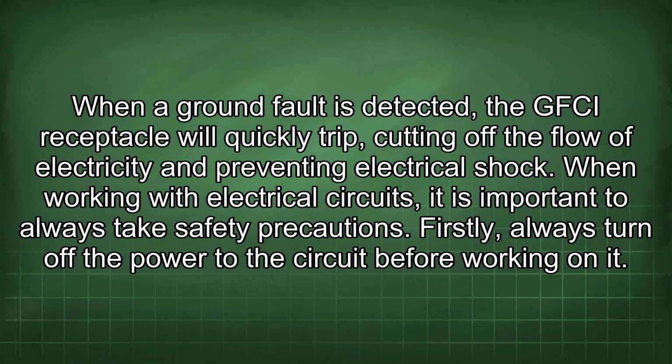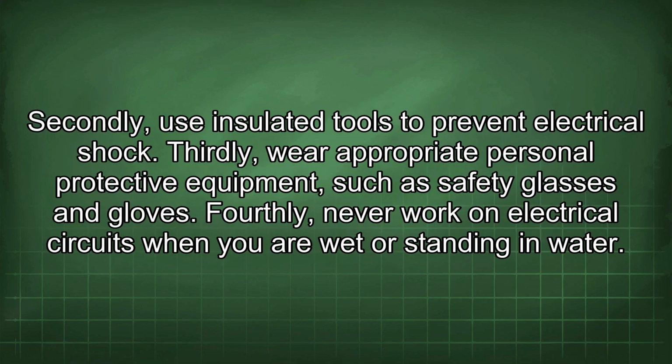When working with electrical circuits, it is important to always take safety precautions. Firstly, always turn off the power to the circuit before working on it. Secondly, use insulated tools to prevent electrical shock. Thirdly, wear appropriate personal protective equipment such as safety glasses and gloves.